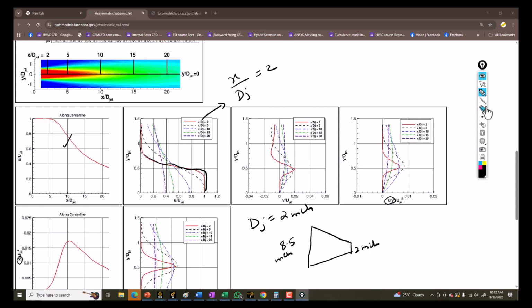Because we are solving this case as axisymmetric, we are only modeling the half nozzle, and we are defining this as the axis. Definitely we have defined the outer profile also and the free stream domain, because the flow will be exiting to free stream, and that's how a nozzle works. So we have to model the free stream domain as well, which I did already, and you have seen that in the slides in the previous videos.